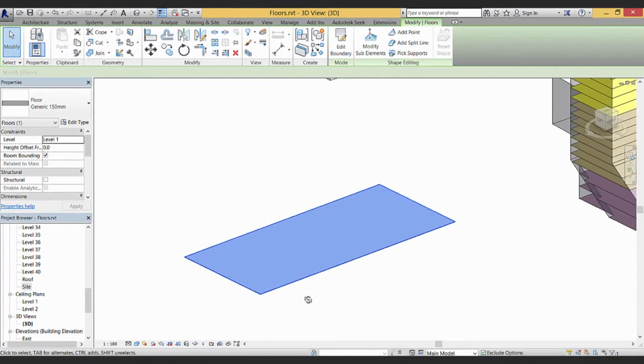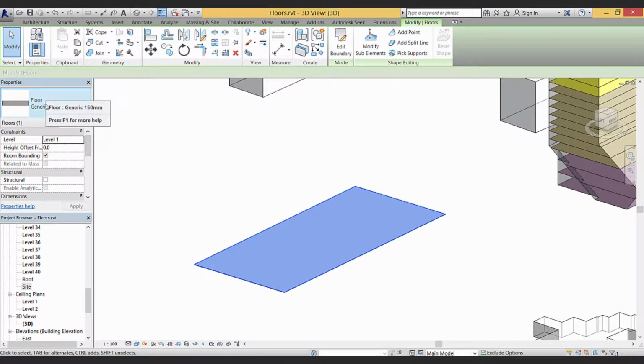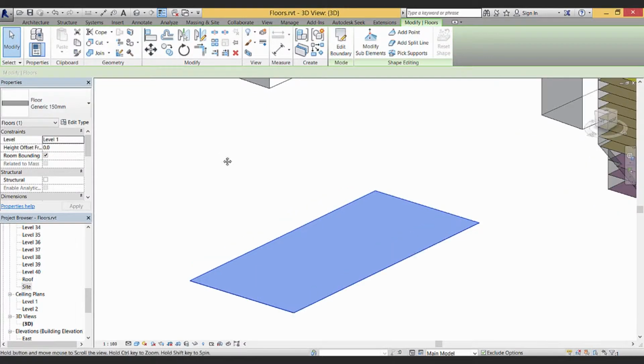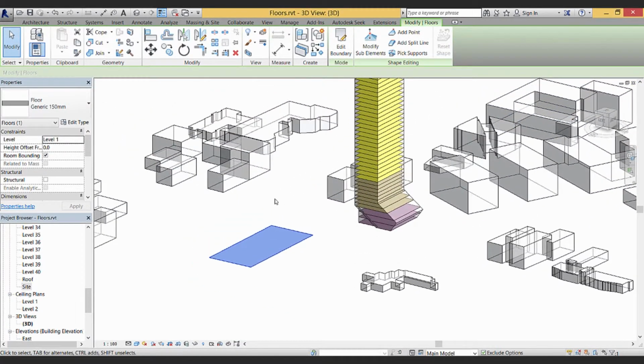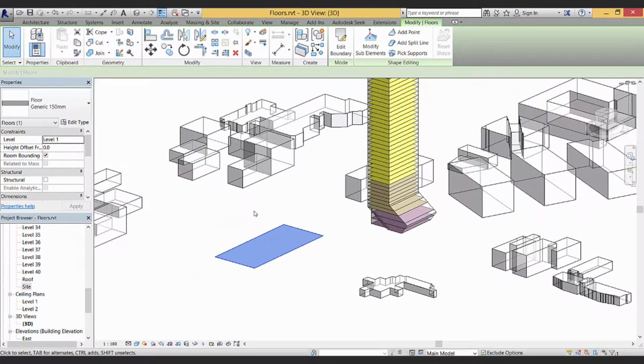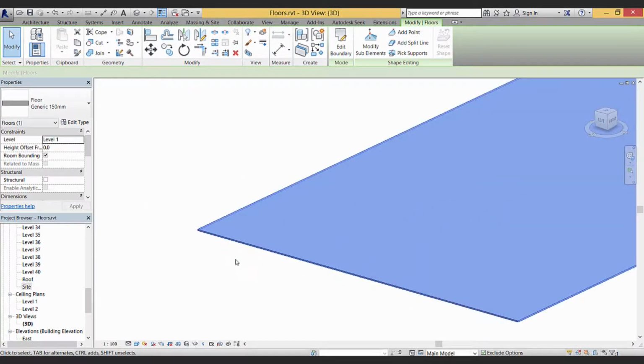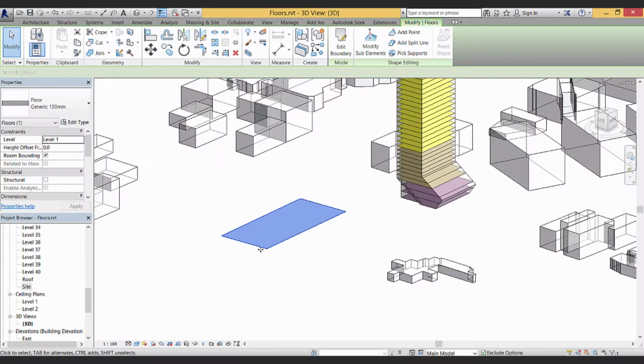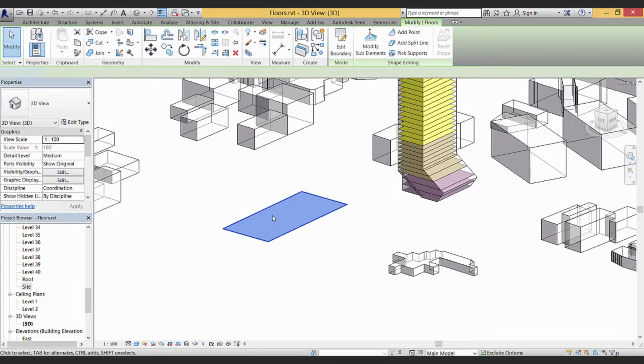Now, this is a floor element inside Revit. It has a category, Floor, it has a type, I'll get back to types, it has a set of parameters, just like the mass floors or views or whatever we selected earlier. It has a thickness, it has a material, and so on. You can edit this floor by double-clicking on it.